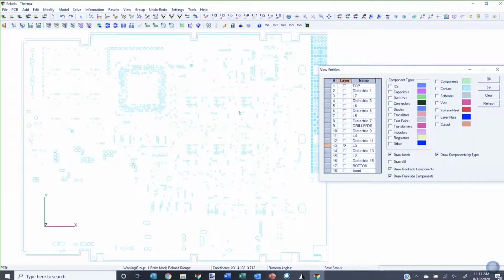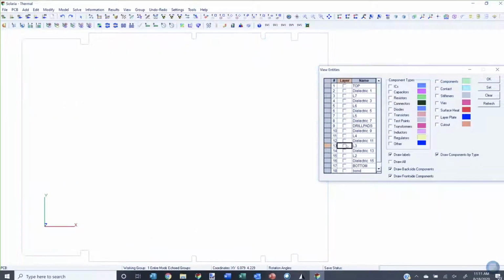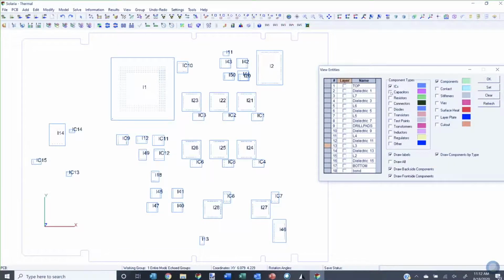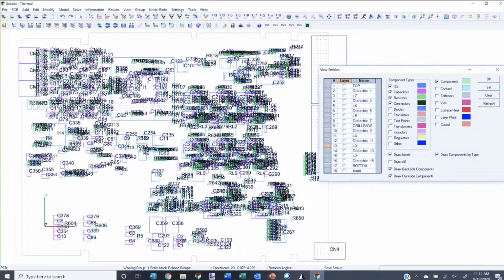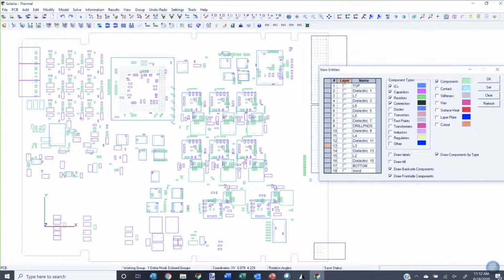When it's in a hole like this, it's sort of isolated thermally as well as electrically, and we account for that in the simulation. So we have all of that information available to us, and that's the advantage in importing an ODB++ file. When you're doing a simulation and your design is utilizing the board as a conductive path, it's important to accurately simulate it.